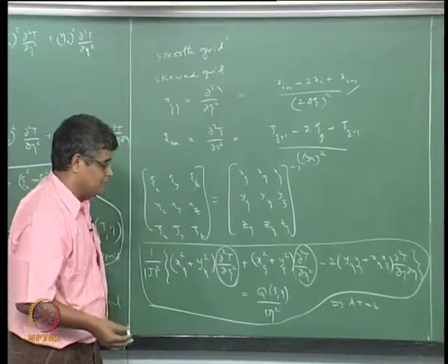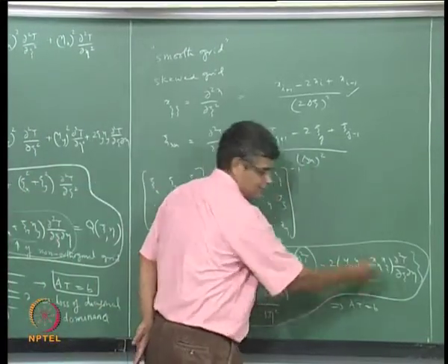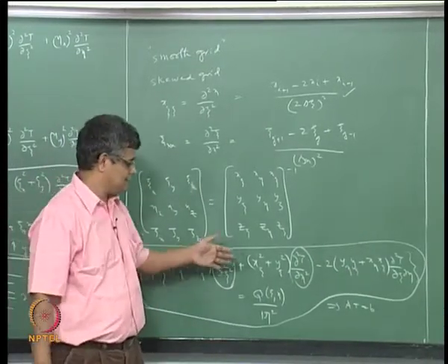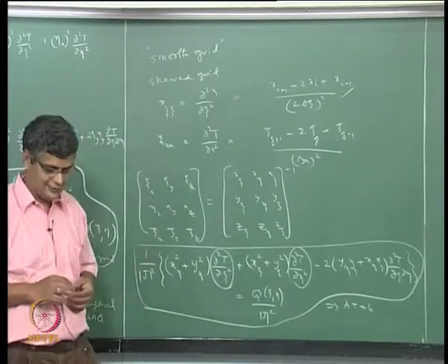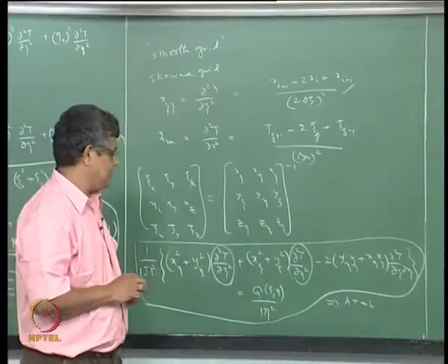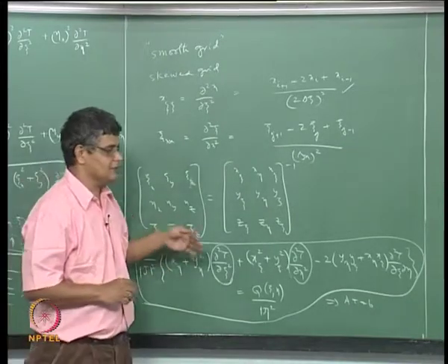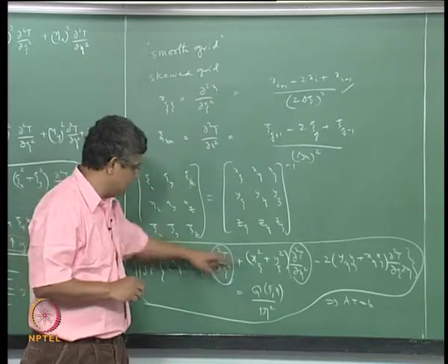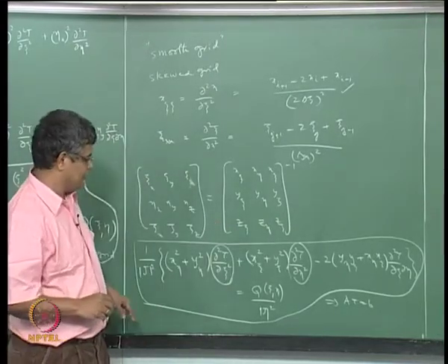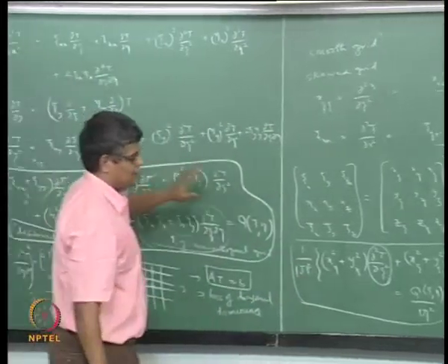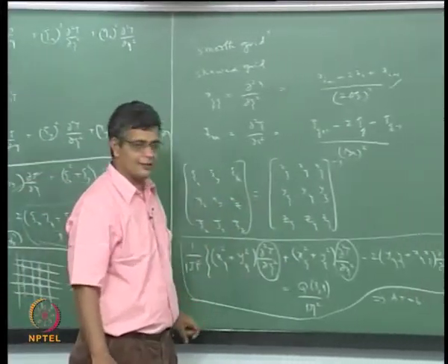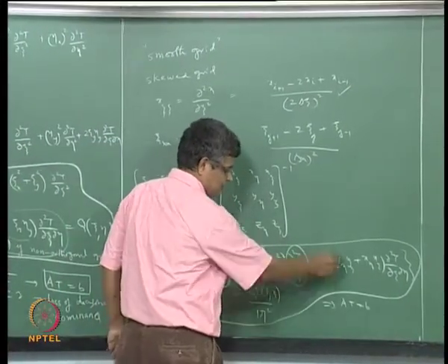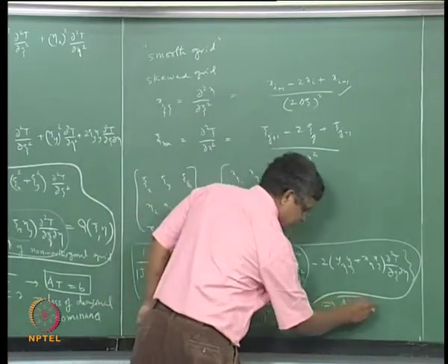And for good measure, because we are getting extra terms in this, we will have to do a stability analysis to see that the discretization scheme that we have got is reasonable, and we also have to derive the stability conditions for this particular scheme with these coefficients that are coming here for the given transformation, and then based on that we finally select a suitable discretization scheme, and then using the discretization scheme we convert the transformed equations into AT equal to B.